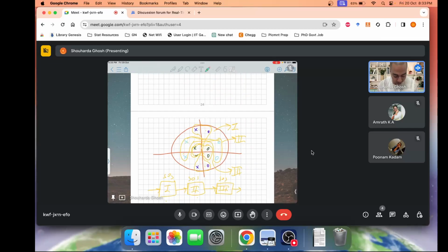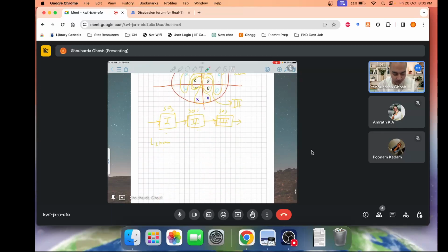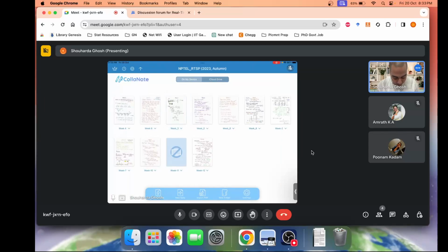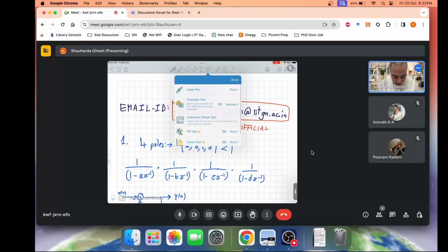And now when we have to make second order systems, we need to pair poles and zeros correspondingly. So we first pair the pole and zero closest to the unit circle, then the next closest, and then the least close. All of this is also mentioned in the book by S K Mitra on digital signal processing that I referred to long back. That was week 3, I guess. Here we have week 4.